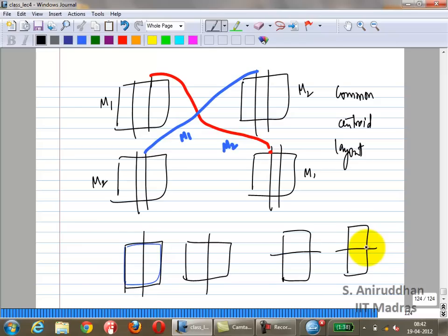The reason is you can have what is called shadowing. You can read up on this in Razavi's book. So when you have a source drain, the implant doesn't come straight in, it comes in at an angle. Okay? So what will happen is one side will get shadowed, and that will affect the transistor next to it.